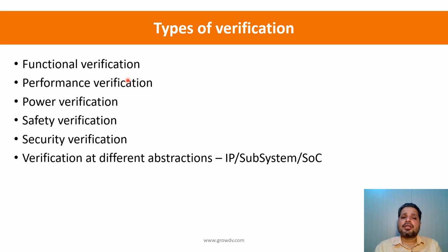All that can be simulated, to check when one particular power island has been turned off, whether the rest of the design can still function properly or not. Those guys also use the test bench that is built by the functional verification team, and they run selective tests which could power on or power off certain islands to see whether the functionality still remains intact, and there are ways to also do some approximations about how much power is being consumed. So all that comes under the power verification purview.